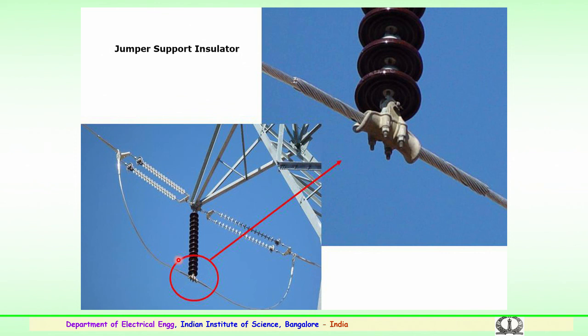So, this is very important for the transmission utilities, to maintain the clearances from the tower ends, the metallic ends, to the conductor. That is the reason you use a suitable suspension or a suitable V type of suspension arrangement to make the necessary clearances and use jumper support conductors of the same dimensions as the conductor. So, these jumper arrangements could be a twin conductor, a quadruple conductor, a single or more number of conductors, depending upon the transmission line which is being connected. So, this again varies for the voltage levels.